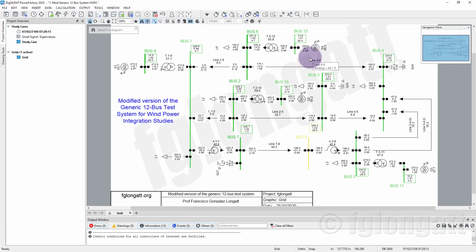As you can see, there are some results, and I will focus specifically on the area between bus bar number 7 and bus bar number 8. Okay, we will focus on that area. You can see there is a power flow going from bus bar number 7, 102.5 megawatts departing from bus bar number 7, and then 106 megawatts arriving at bus bar 8.